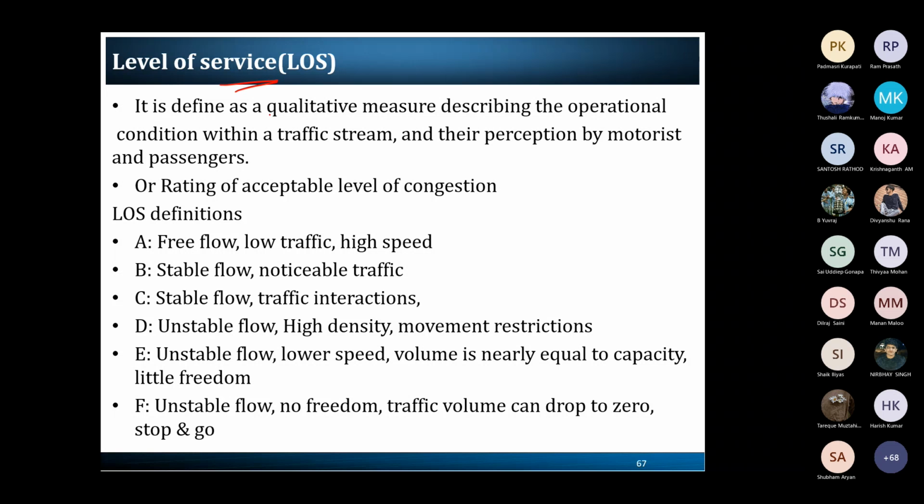So you might be studying the flow, density, speed, travel time, capacity, everything together, and you are rating A to F, maybe rank A to 6. So from the Pavement junction to NIT Trichy, it is performing at the F level of service. Maybe the intersection is performing at level of service B. So what are these A, B, C, D, E and F? That is classified here with respect to the standard study.